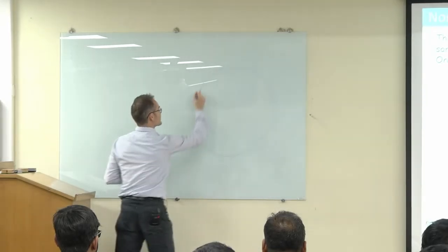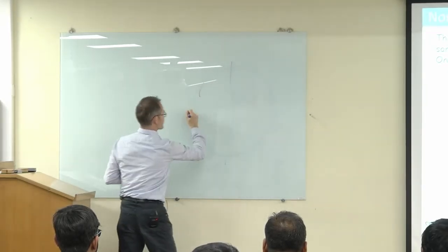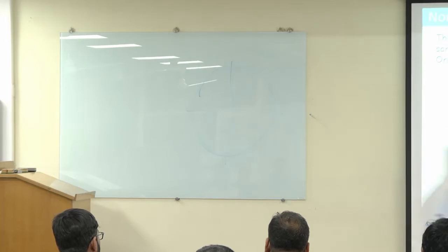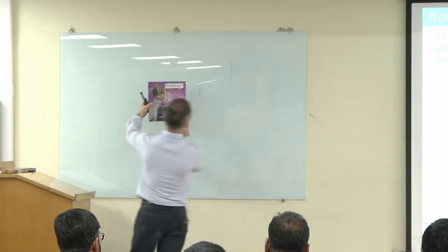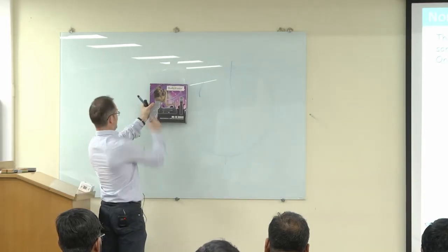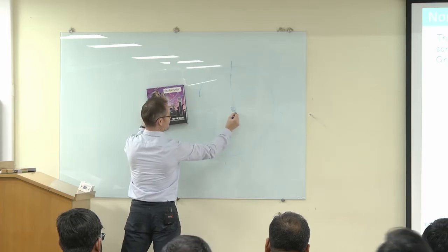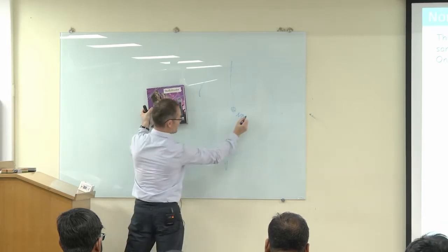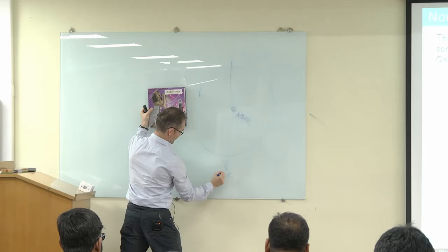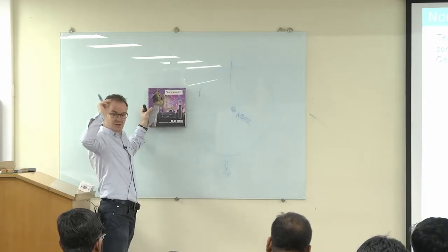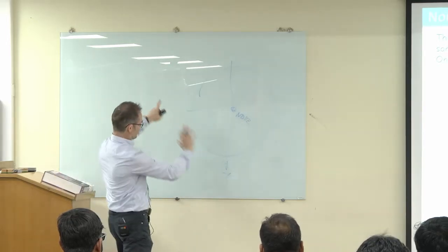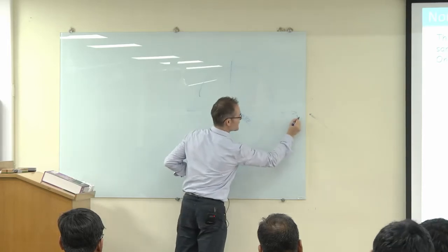Again, our stereographic projection. And I fix the stereographic projection such that it will represent my fixed sample coordinate system. So I will say here in the middle, this is the direction ND, which is perpendicular to here, we call it also Z, and this one will be X. Whatever this X means, it could be rolling direction, extrusion direction, shear direction, whatever you fix it. Good. And now it's fixed, and of course then here is Y.